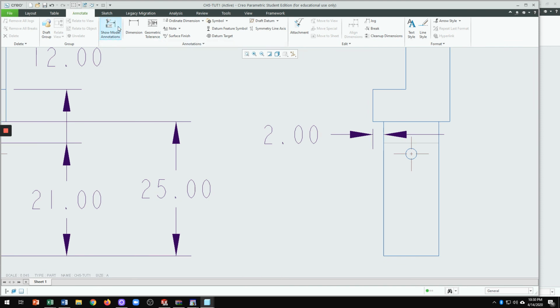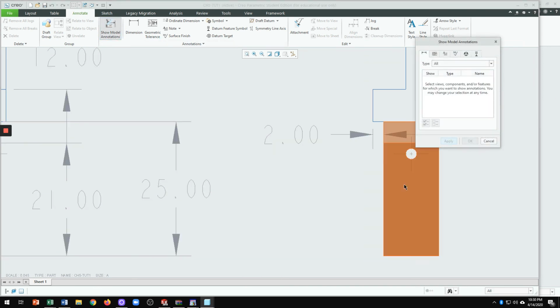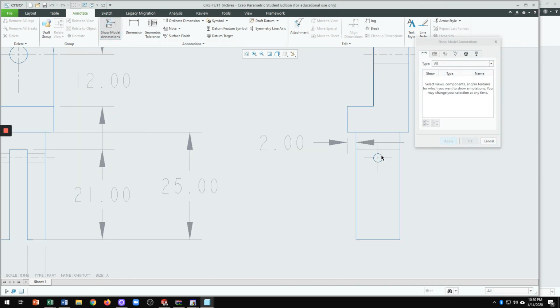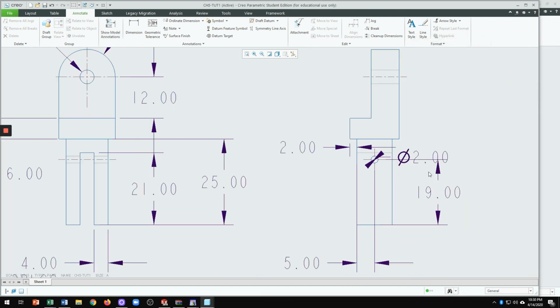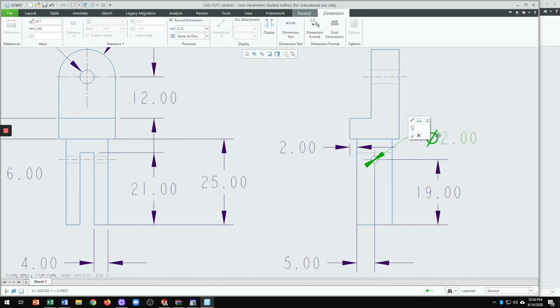And then if I wanted to go back to automatic dimensioning, I can click on that, and then remember, by clicking on the circle, all the measurements I gave during the sketch popped up, or appeared in here. So I'm going to do a little bit of cosmetic work because it's overlapping.